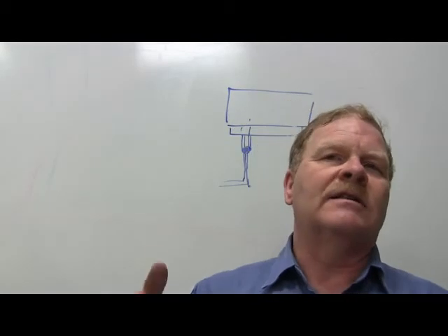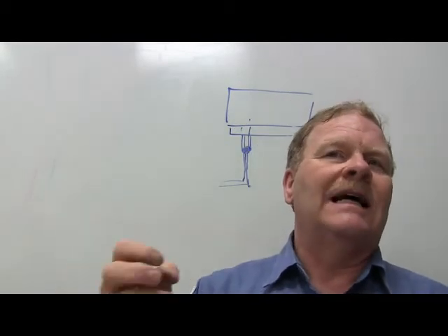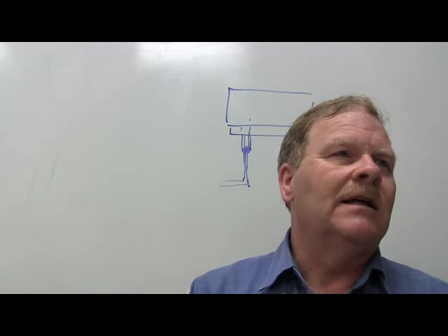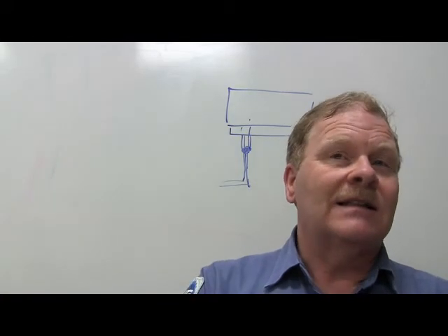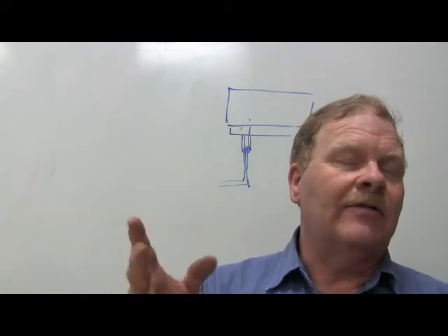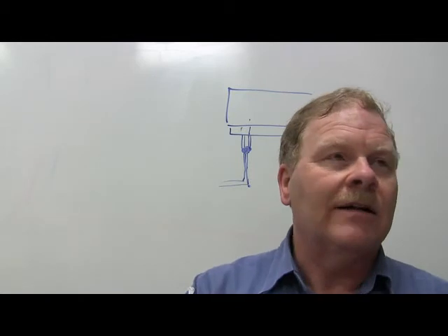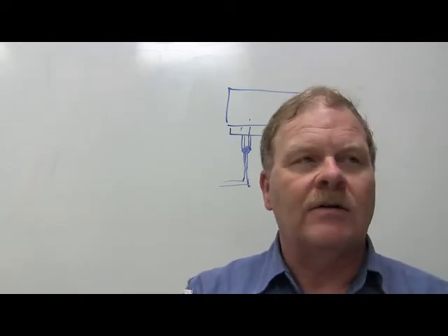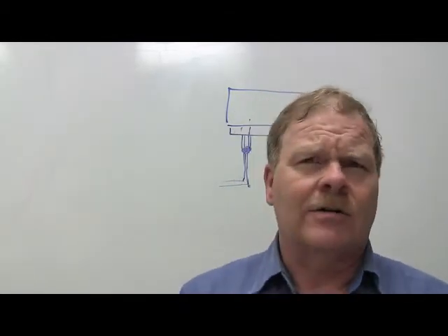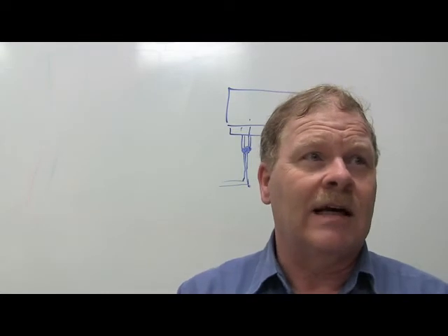Basically, you wind up with resistance and oxidation there, and it starts to heat up because of the resistance. The resistance is keeping the current from going up high enough to blow the fuse, but at the same time it's melting things. Anytime you've got resistance, you've got heat. I had a Chrysler instructor one time that tried to say resistance didn't make heat.